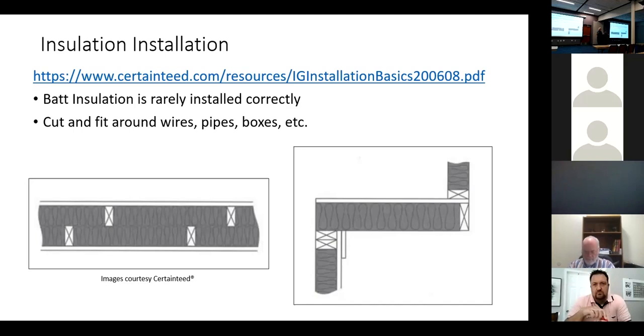All of a sudden, everything works great. You find when you work out in the cold, you put on all these layers, we have all this air, and then the last layer is an air barrier, so the air doesn't move through it. As soon as we start moving air through our insulation, the effective R value just plummets. And so the code really is clamping down, because of building science, on any vertical insulation, which includes rim joists, because we get those convective flows in the rim joists.